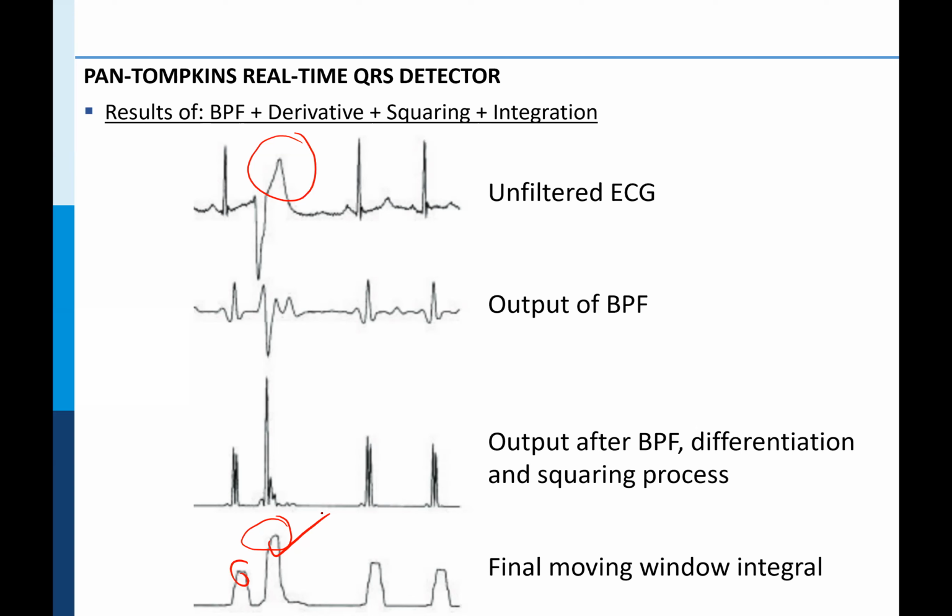Just to point out how we can turn around these various outputs in a way that you want it to adapt to the application at hand. So in addition to measuring the number of beats, which is measuring the number of QRS complexes, and measuring the width of the QRS pulse, we can also see the measurement of arrhythmia, or appearances of instant and rapid beats next to each other.